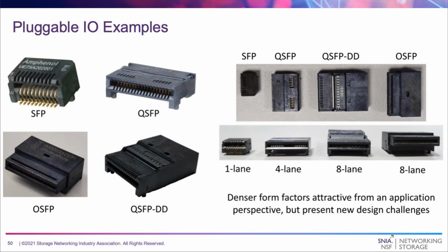And then lastly, OSFP is also an 8-lane interface, slightly wider and larger than the QSFP-DD. The additional width isn't twice the QSFP-DD or QSFP form factor, though, and that's because the contact pitch is actually reduced down to 0.6 millimeters. And we did mention OSFP-XD, which is a newly under development standard, and that combines the 0.6 millimeter pitch of a traditional OSFP with the double row of contacts like the QSFP-DD solution.